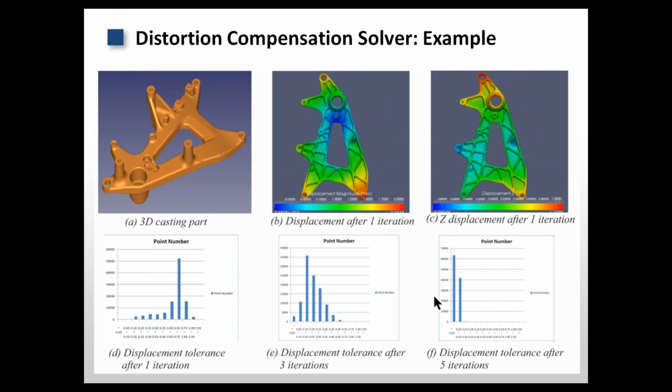Please notice that if you set a very high standard for the deformation, it will not be easy to find a solution. So this is something you need to remember: not all targets can be reached if you input unrealistic requirements for the casting part.